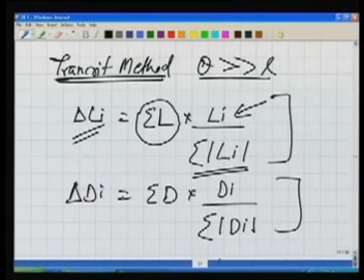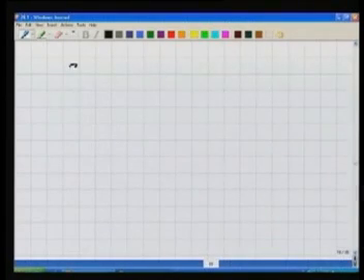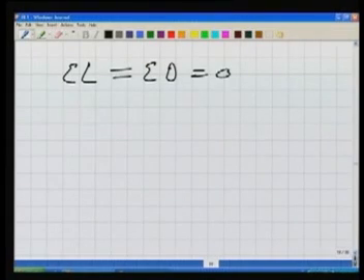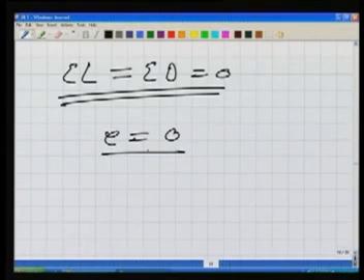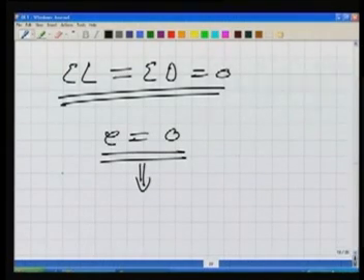Once we apply the corrections this way, it will be ensured. You can do it in a numerical now, this will become 0. If it is so, our misclosure error is also 0. Henceforth, once we have done it, we can compute our independent coordinates, and then we can take those coordinates to any software or to our drawing sheet and we can plot the map.